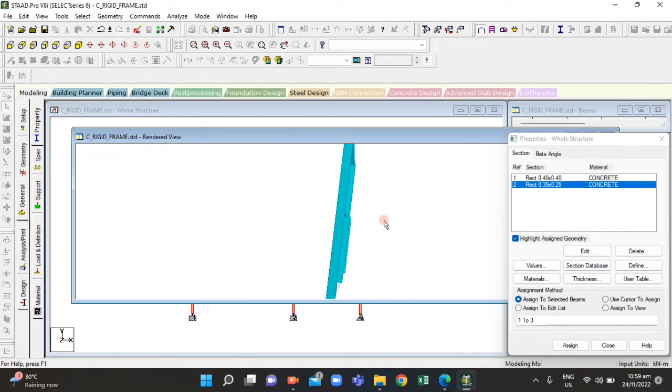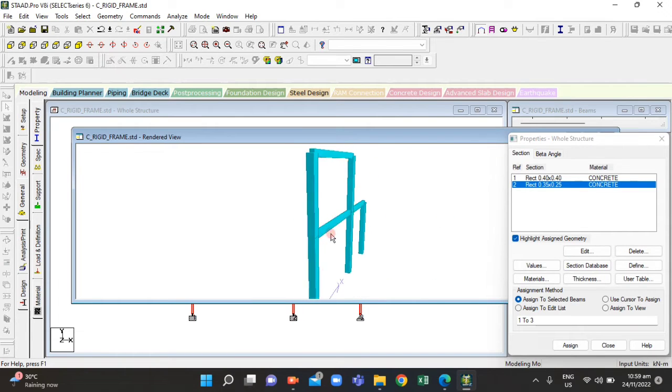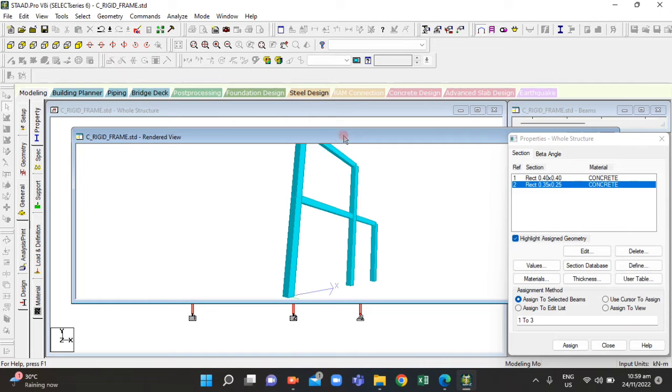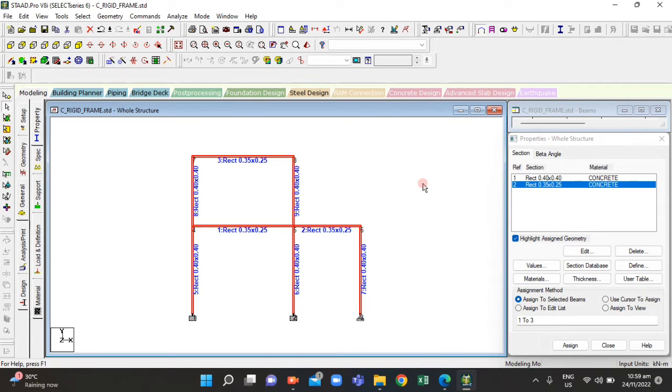So you have the thickness, the width, the length, and the height, compared to the unassigned sectional properties. It will only render a line view, just straight connected lines that represent the beams and the nodes. So after that, I'm just gonna X this, so that's already verified. So what we need to do now is to apply the loads.